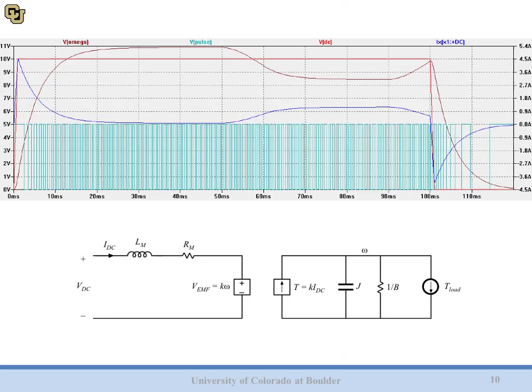And if you were to do that, you might get a plot like this. You see we have V omega. It thinks it's a voltage, but really we know it's an angular frequency, so make sure you scale accordingly. And there we have our turn on transient and turn off. You can see our encoder pulses in kind of teal down here are nicely generated from that separate block. And we have things like our motor current, the DC input voltage, and the encoder pulses.